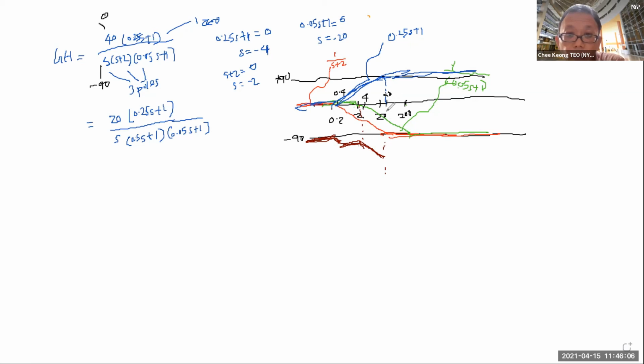So there's flattening, all the way up to 40, because at 40, the other guy also stops. So it's flattened at 40. Then, of course, after it flattens, this guy also stops at 40, then you will follow this guy at minus 20 dB per decade, and when you hit 200, you will flatten.